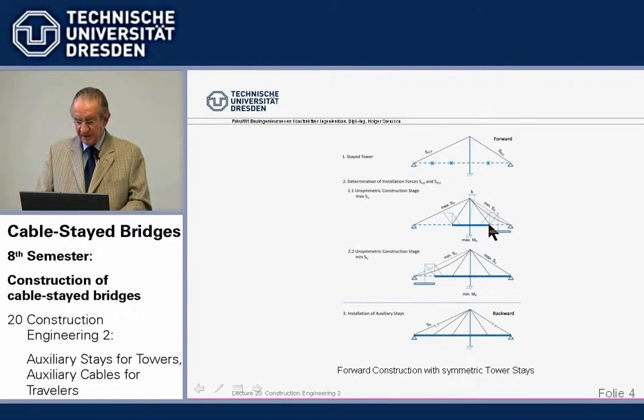Governing is here for the side span loading, the before closure here at the side span, so lifting the element with the biggest lever arm, say 300 tons, with the biggest lever arm, which means we have the biggest force in this backstay cable. So in there is the maximum force from lifting plus a minimum force for, say, post-tensioning at the beginning.